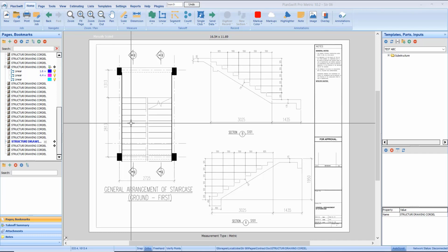But you have to understand that taking measurement for your staircase work is majorly in three places. For now, we'll be talking about the measurement of our staircase in terms of the in-situ concrete work. Then we will also touch on reinforcement, but as it concerns formwork, we might not go into that. If you are able to take off for your concrete work and for your reinforcement, then I see no reason why you shouldn't be able to take measurement for your formwork.